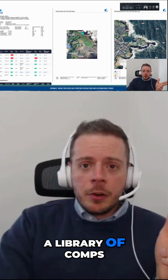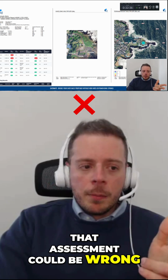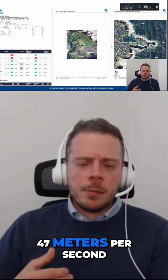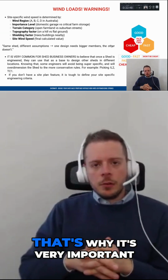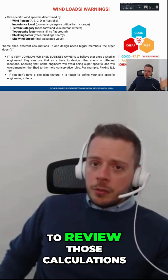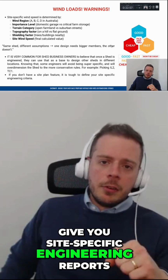So if you're using a library of computations and it's exactly the same, you're not using site-specific, that assessment could be wrong because the wind in this case is, if I'm not mistaken, 47 meters per second. So the wind loads can be a problem if you're not using site-specific. That's why it's very important, especially after 2021 with the updates, to review those calculations you have or use a system that can give you site-specific engineering reports.